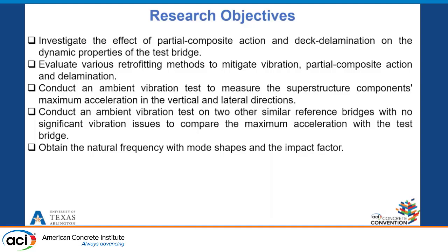Its specific objectives are, number one, to conduct an ambient vibration test on the subject bridge to measure the superstructure component's maximum acceleration in the vertical and lateral directions. Number two, conduct an ambient vibration test on 2 other similar reference bridges with no signs of a significant vibration issue to compare the maximum acceleration with the test bridge.